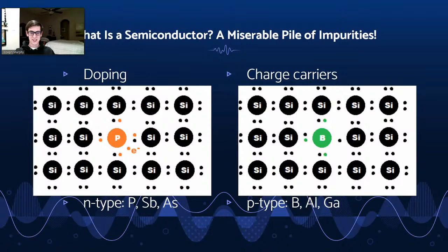So what happens? Well, let's say that one of the boron's electrons decides to move from its current bond over to complete the bond in the other location. Let's say the top electron of this boron moves over to the right and forms a bond there. Well, now we've completed the bond, but we've just created another gap up top, right, where we still only have one electron. Nothing has really changed.